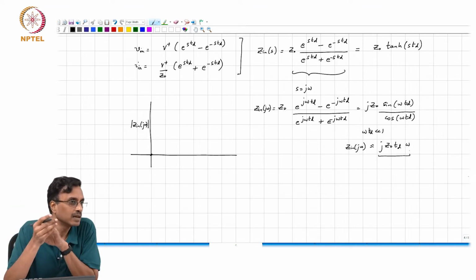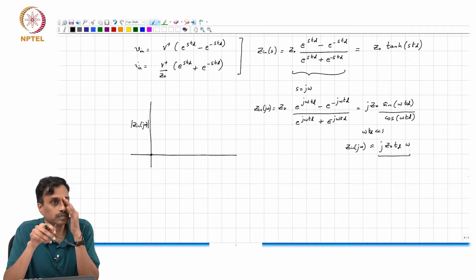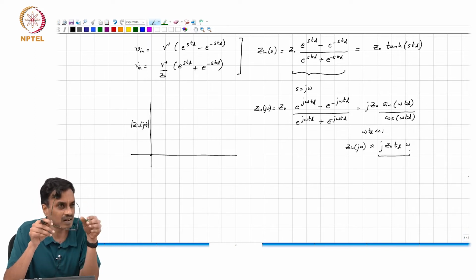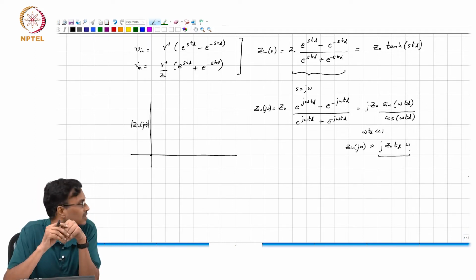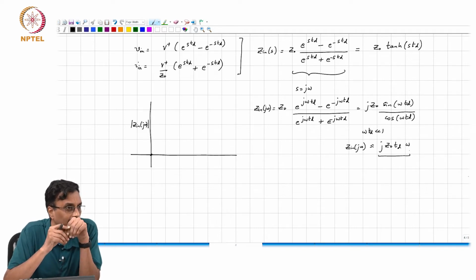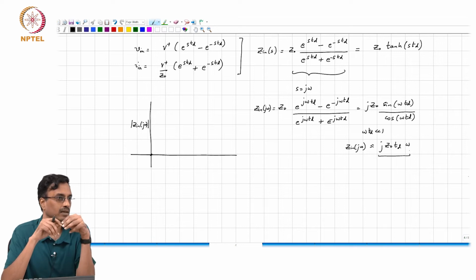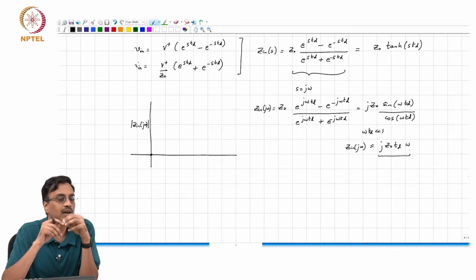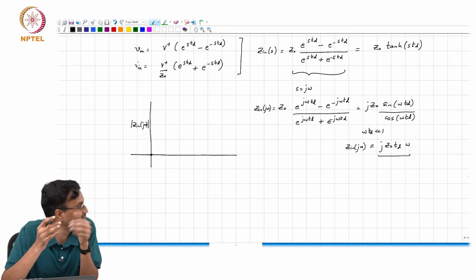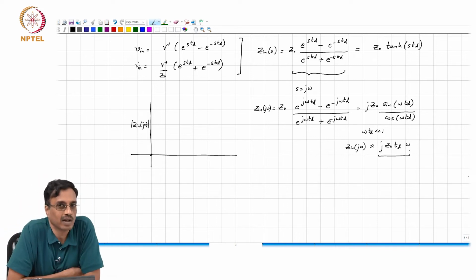This is an inductance. So, why does this make intuitive sense? Yeah, inductance is a short, but I am asking you what is the value of that inductance? Z naught times Td, correct? The question is, why does this Z naught times Td make any sense, or do you say, well, what can I say, it comes out of the math.